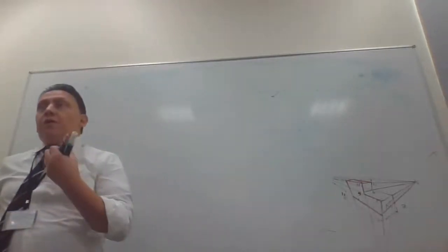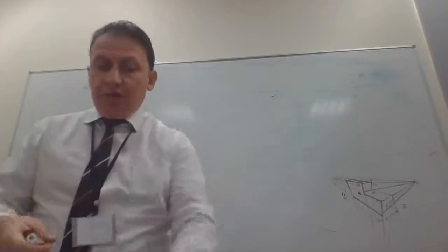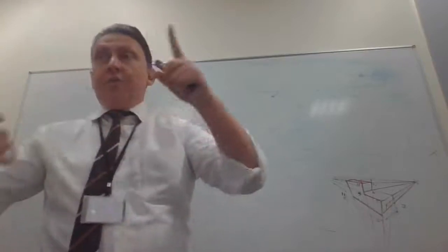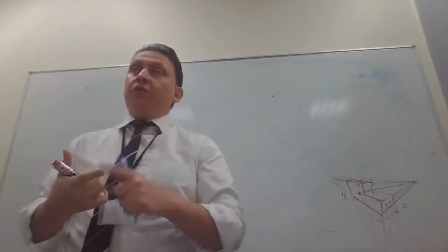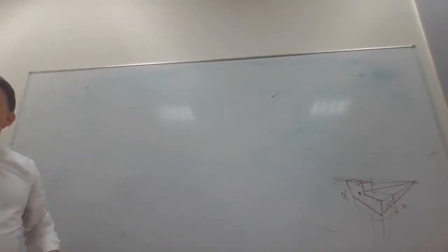One more time. What are the conditions for isometric view? We said we have to keep the lines what? Parallel. Parallel, number one. Number two, which angle we have to draw? 30 degrees from right, 30 degrees. Bravo, bravo. Okay, so let's start with a simple object, okay?